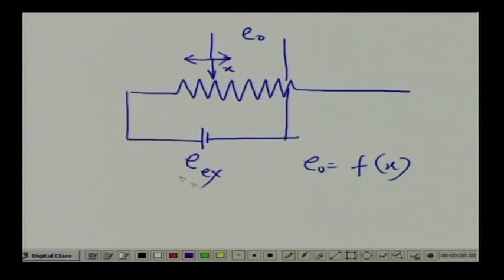its resolution. The resolution of the LVDT is extremely good. Please note that good resolution means its numerical value will be less. Another thing is that sensitivity, in both cases, I can change. I can change the excitation voltage Ex; if I change the excitation voltage, my output will also increase. But I am not talking about this, I am talking about the resolution.